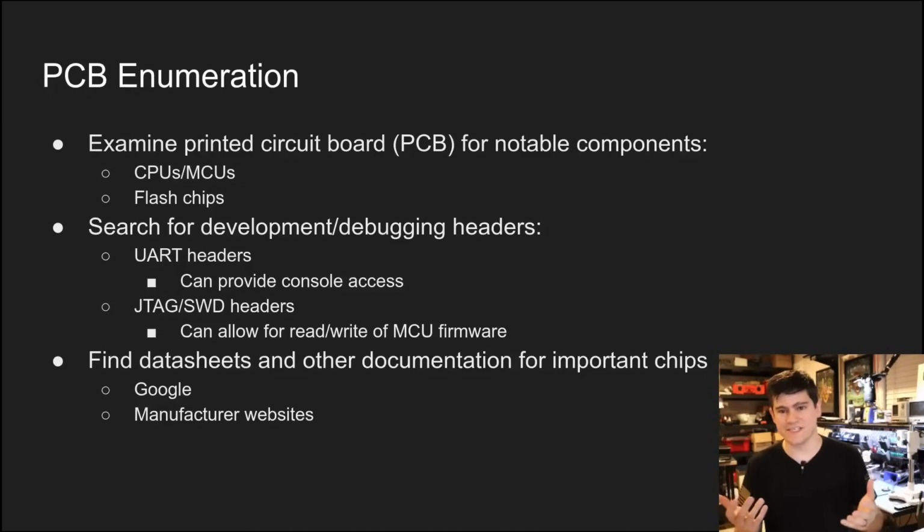Whereas on a Linux system, it's a discrete chip that you can easily desolder and throw in a flash reader. But oftentimes the only way to get at the memory, the firmware of a microcontroller is through one of these debug protocols. So we want to check if those are enabled.